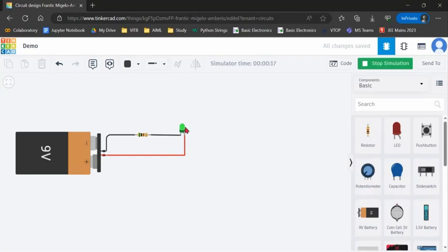So whenever we connect a load, like an LED bulb, whatever current is passing through this LED should be within the upper limit. Its maximum limit is 20 milliampere, so it has to be less than 20 milliampere so that its lifetime is improved. If we are using an LED, we should connect a resistance. In the lab session, when you use the practical components, whenever you connect an LED, make sure you use a resistance, and the resistance should be a minimum of 500 ohms, so that the current reaching the LED is within the permissible limit.